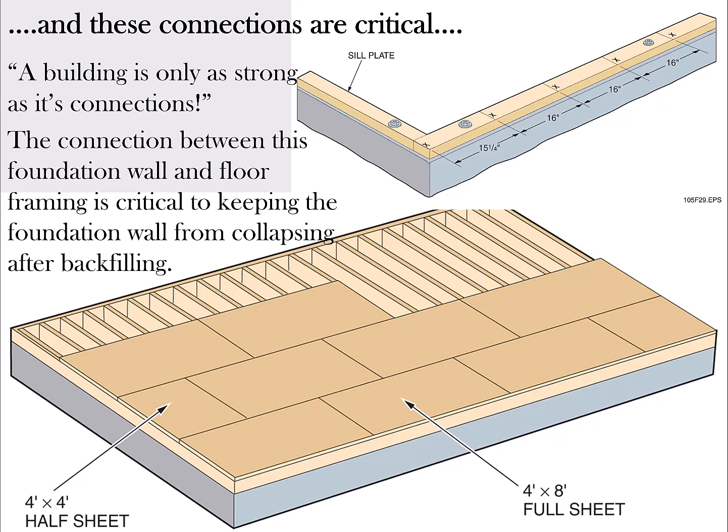There's metal strapping that we'll use here in Louisiana, in the South, when you have a slab on grade, to hold that wall down, because you're not trying to brace a foundation wall like this. No basements, but in a basement you typically need anchor bolts at a certain pattern, and what they're trying to show, I think, is the idea that you put the bolts where they won't interfere with the studs.